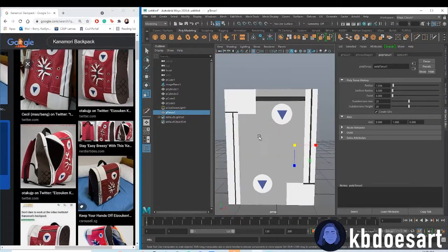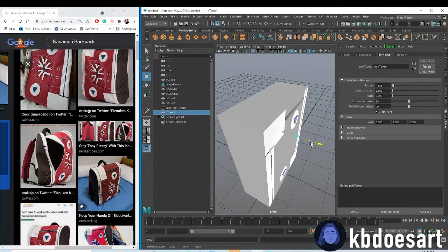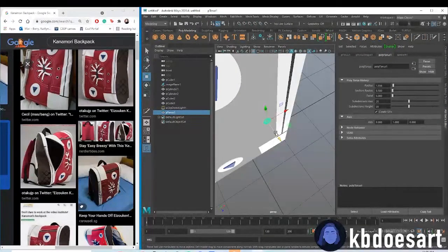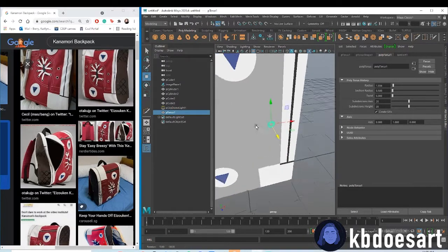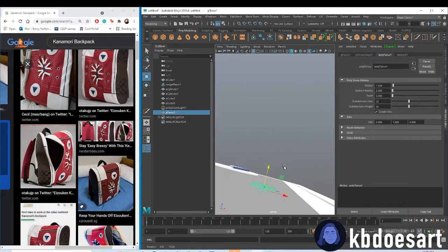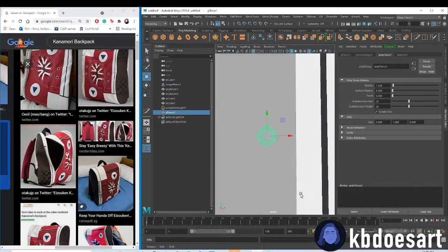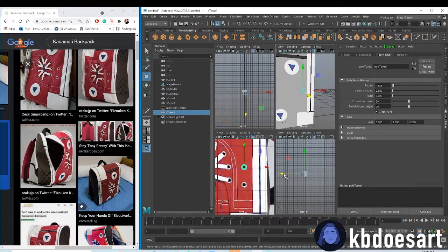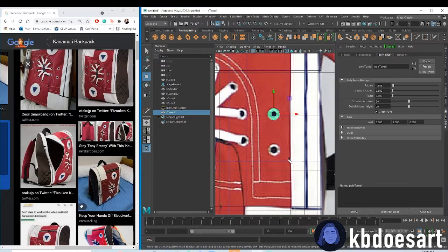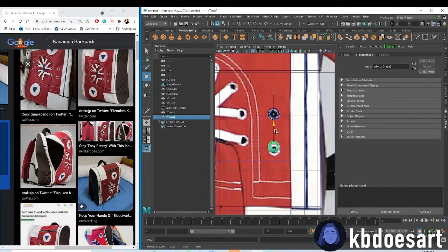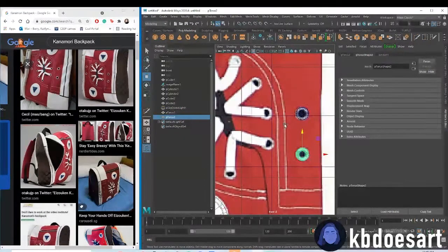And then let's push it on out over here. Obviously, it's got to clip that surface. So you can just decide how much you want to clip it, maybe like that. All right, and then you're gonna just duplicate it and move them around. So Control D is duplicate, and then just click W and move them.